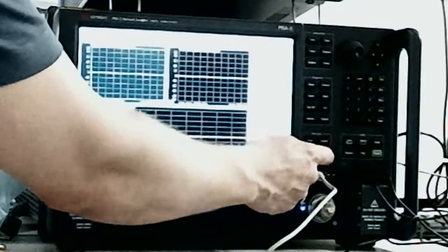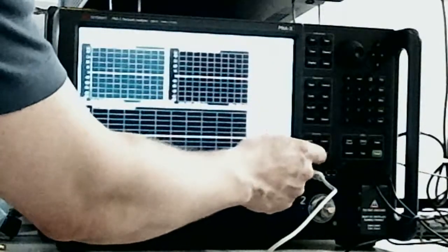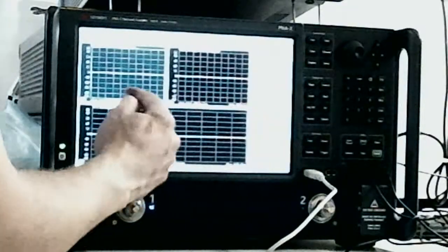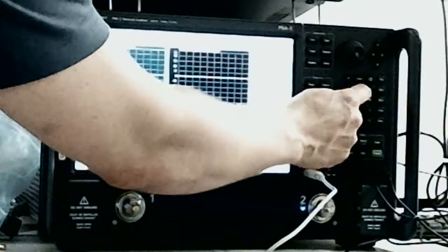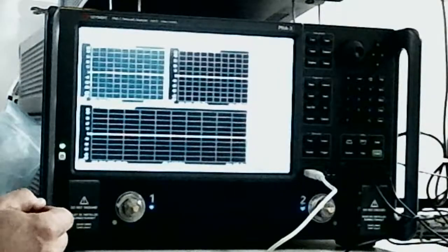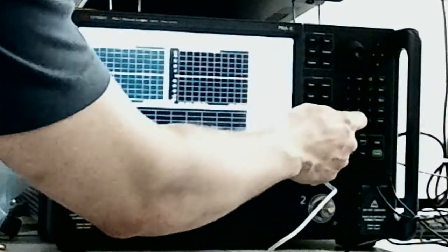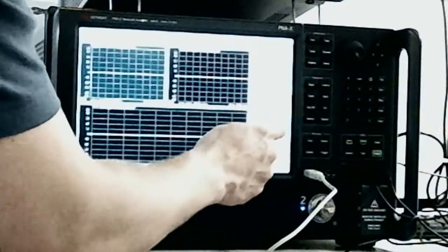But I'll just set this up over here, and I'm going to go power again. Actually, sorry, let me go to sweep. So another power sweep over here. And then for this one, maybe I'm interested in seeing if this also works at 5.8 gigahertz for some of the other Wi-Fi applications. When we go start, it's minus 20 again, and then frequency is 5.8 gigahertz.